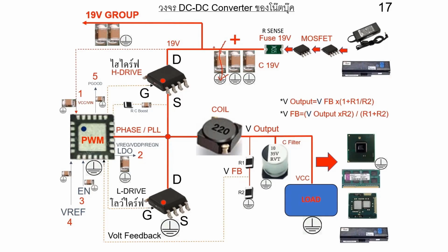But if it's a fake short, when you check it with the probe, it's shorted together, but we still measure 49. The reason it doesn't drop to 0 at all is because there's another MOSFET acting as a barrier, so it doesn't flow down to this point here. This one isn't shorted, this one is okay. That's why the measured value isn't 0, you get what I mean? So if the MOSFET or something is shorted, the measured value won't be 0. But if it's a C short, the measured value will be 0.